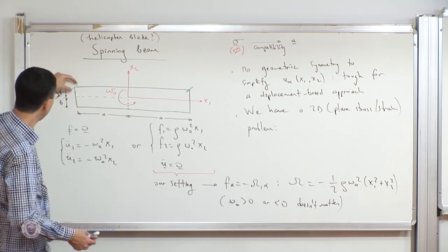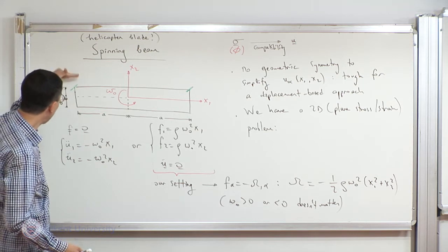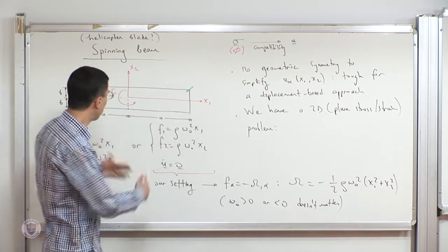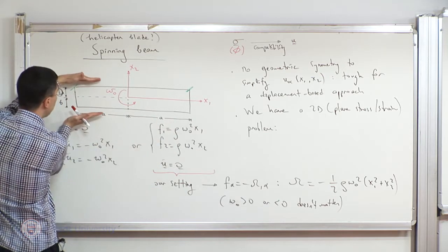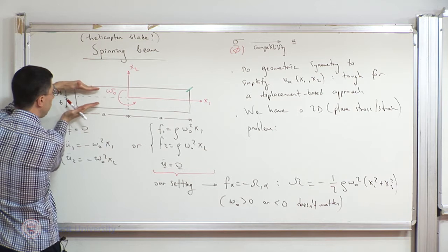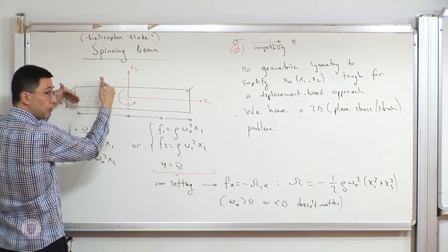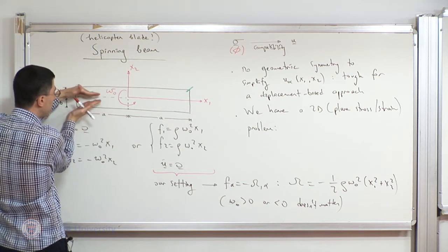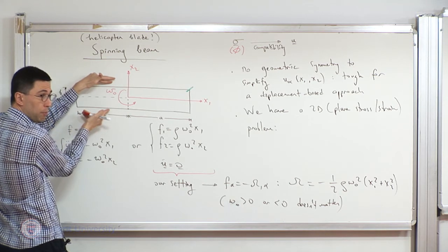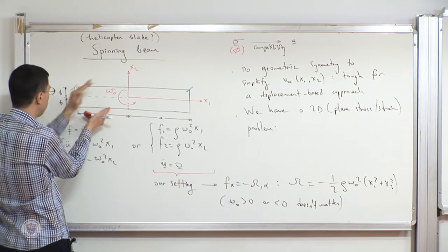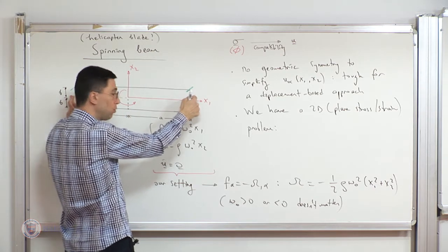So ideally, that case is achieved when the thickness is very, very thin, right? But there is a height and there is a length, or a width. So it's 2D. But now imagine additionally that the height is very small. So then you're omitting the third direction, as it becomes very, very thin, and you notice that we have eventually stress-free upper and lower boundary conditions here. Traction-free. Also, the left and right edges are also traction-free. Eventually, we're going to make use of those facts.